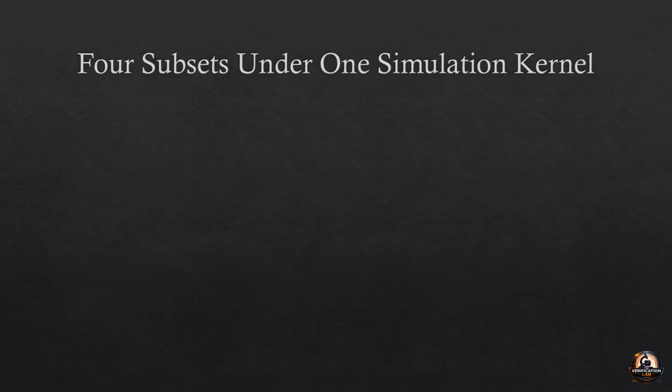So four subsets under one simulation kernel. We don't need different simulation kernels here. SystemVerilog has four subsets and we will be discussing all of them. First we are discussing the design constructs. SystemVerilog has synthesizable RTL constructs. Synthesizable means those constructs can be translated into actual hardware. That means flip-flops and all the actual hardware required to draw a circuit.